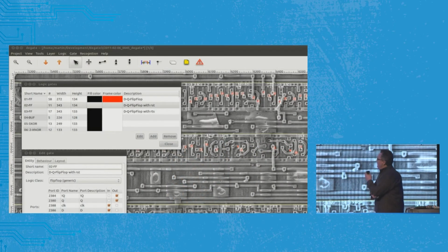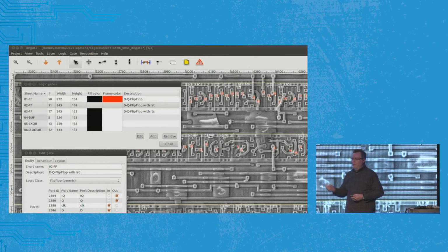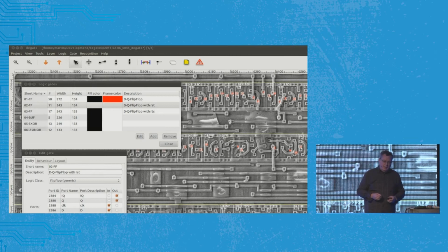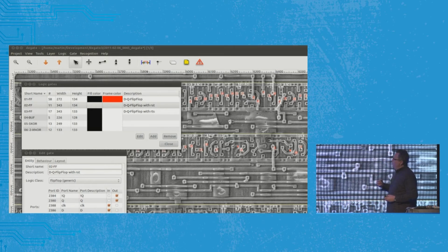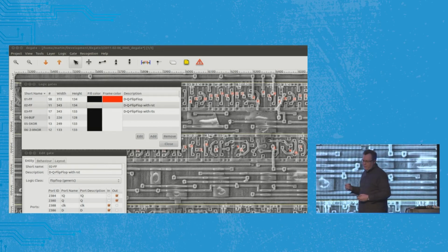Another area really is, if I look at the metal layers, I can also look at some of the logic there. So while I might have memory areas where I'm going to store the dynamic memory, or maybe some of the original memory that was put onto the chip, I can also look at some of the secret source routines here. Once you get good at these, you can actually start programming a system to do image recognition to identify, for example, the flip-flops and the logic gates that are part of this particular system. And folks that do this quite a bit become very good and become experts at spotting where the cryptographic routines are and spotting flaws in the cryptographic routines purely from looking at the pictures.